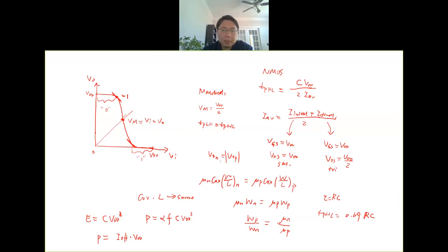So to make this matched condition, you need to satisfy some criteria here. So first is this threshold voltage for the NMOS equals the threshold voltage for the PMOS, of course, absolute value. And then second one is this coefficient in front of that voltage term in the current equation. Is this mu n COX W over Ln should be equal to mu p COX W over Lp. Basically, the strengths of the NMOS and PMOS are the same.